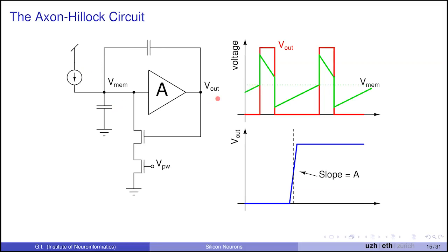And you start to measure on the oscilloscope these traces. What would happen was that the circuit would not work at all as expected. And you have to imagine, let's look at this green trace here. In a physical system, you always have noise. So the green trace would be superimposed with small fluctuations that are there due to the noise.